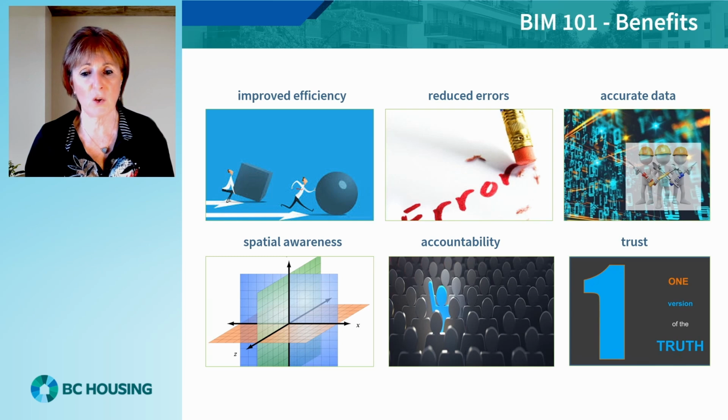It provides spatial awareness by creating a virtual representation of the building project. BIM enables the identification of spatial conflicts between different building systems, such as structural elements and mechanical ducts. Clash detection or virtual coordination helps avoid costly rework and delays during construction.